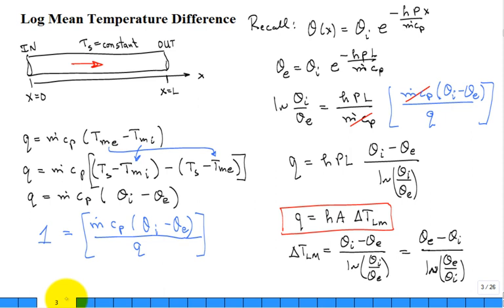We did some calculations. I said, what happens if the temperature difference on the inside, like theta 1, is maybe 50 degrees C, and theta 2 is 30 degrees C, and you want to use a simple approximate equation that says that Q, in the red box right here, is equal to hA times an appropriate temperature difference between the hot surface and the cooler fluid flowing in the tube, and it's the log mean temperature difference.